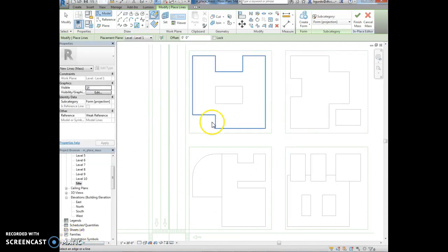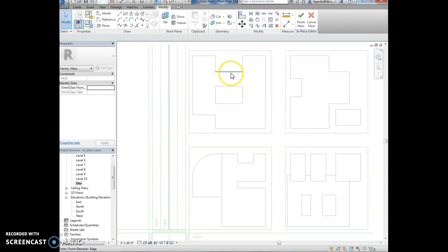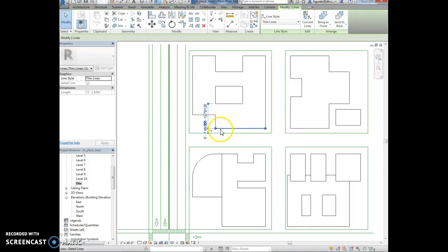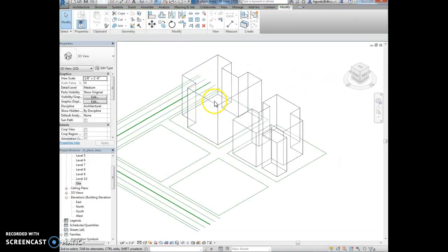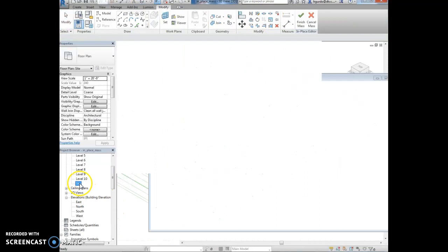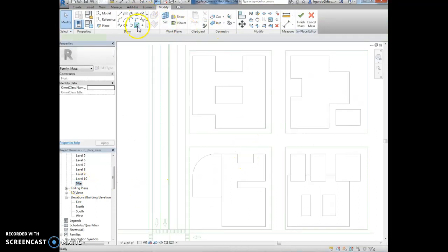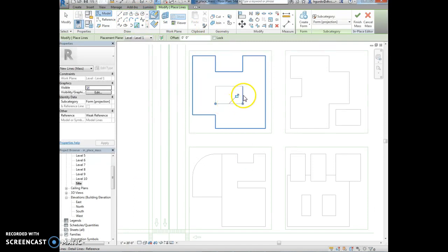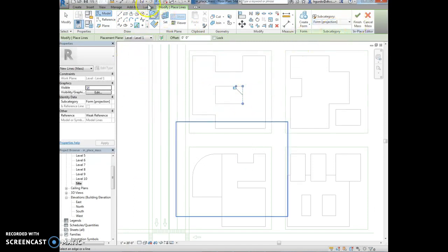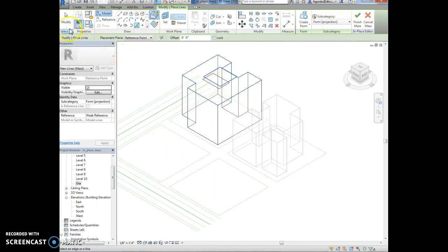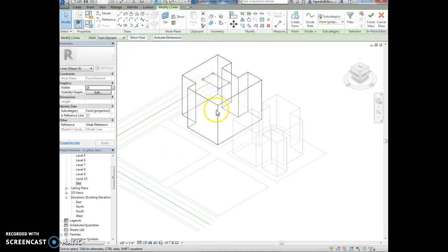Okay, so for the next part, it says to select the inner sketch, which I never did. So I clicked back on my model. Well, here, let me show you. I clicked back on it. 3D, and I said edit in place, and then I looked at it on the site plan, and then I went back and I want to draw this mass around here. Okay, so then I'll go back to the 3D view. So now I have this mass right here. The only problem is that it's starting from 82 feet because its host is now this box instead of the floor. So I can host it from level 1, which then pushes it back down.